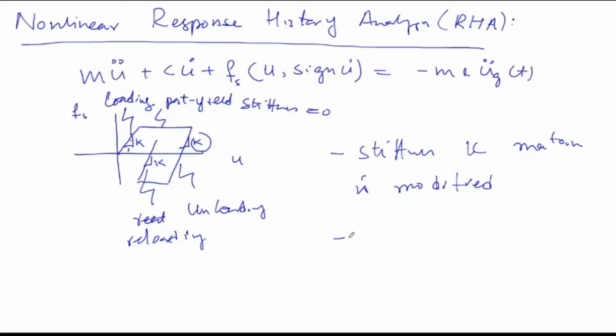Now, in the inelastic case, the force deformation behavior, which is this one, for a structure member undergoing cyclic deformation, is now nonlinear and hysteretic. So you can see the behavior is nonlinear. When we say nonlinear, the fact is that this line is linear, but this is not in the same slope as this, so it becomes nonlinear, and it is hysteretic. If it goes back and forth on the same path, it is elastic. But if it is having some residual deformation after unloading, it means it is hysteretic. It is not elastic.